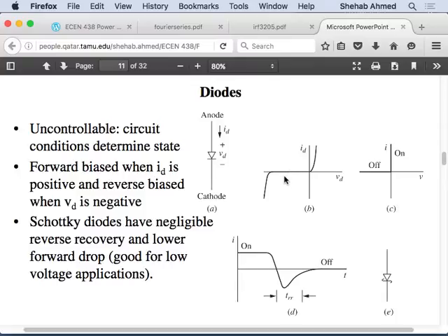Up to some point, you're going to reach a breakdown voltage. Like the Zener breakdown operation, but this is non-reversible in this case for classical diodes, not a Zener diode. You put enough negative voltage so that you basically are burning the diode. You're pushing this diode to an irreversible failure. So this is the full performance curve of the diode.